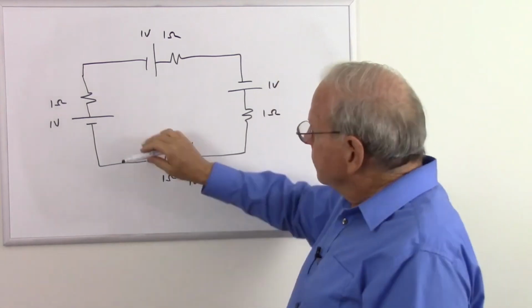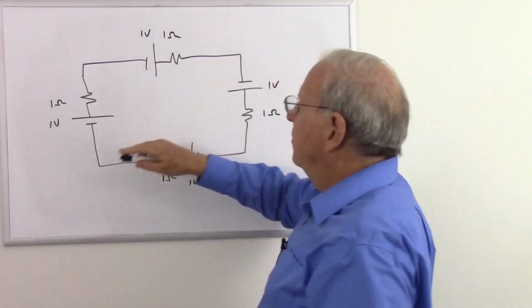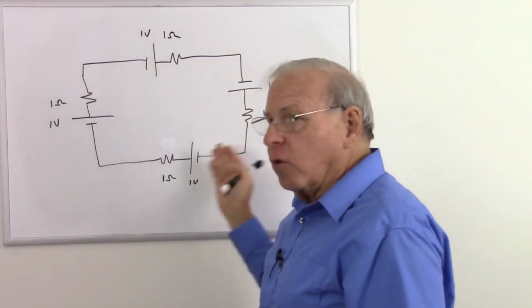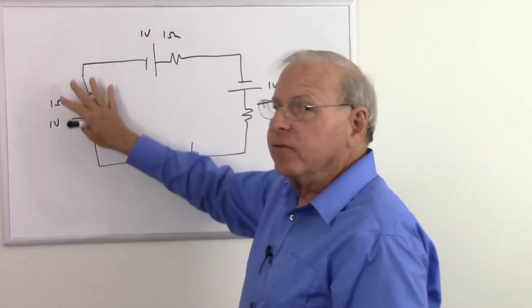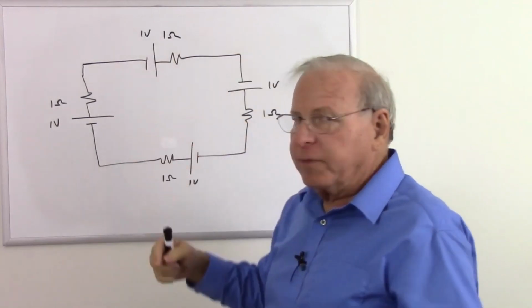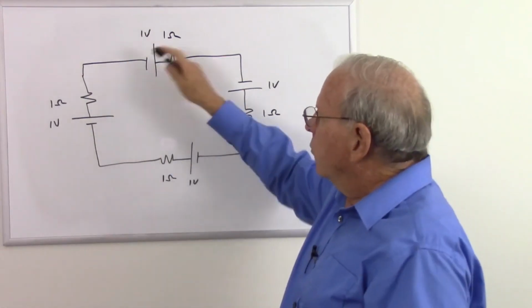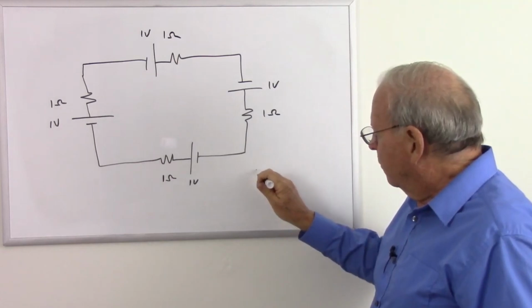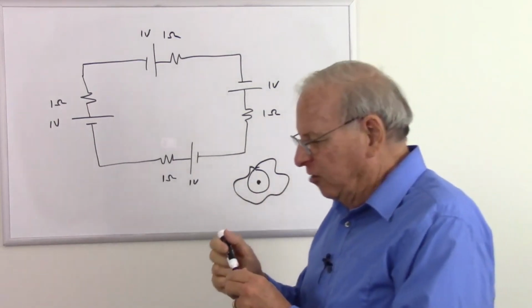Now let's see what happens in this loop. So once again, we have that solenoid that has the changing magnetic field, which is inducing the current, and that means that this is a wire with now 4 ohms of resistance, and at this particular point in time we have 4 volts of voltage induced in it, causing our current to flow. And now we're modeling that wire as the square loop. Does the square make anything different? No, it doesn't matter what the shape is. Circle is kind of convenient for what I'm doing now. The square is convenient, but the shape of that loop around that coil, if here's the coil and the loop looks like that, that's fine. If the loop looks like this, nothing changes as long as nothing else changes.